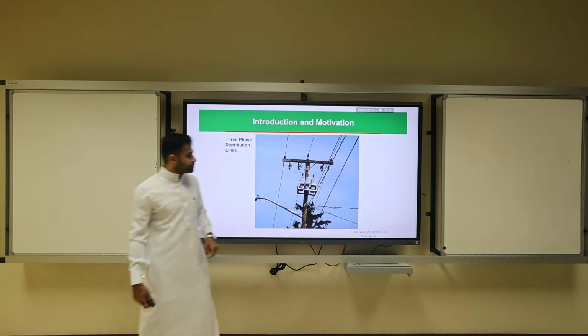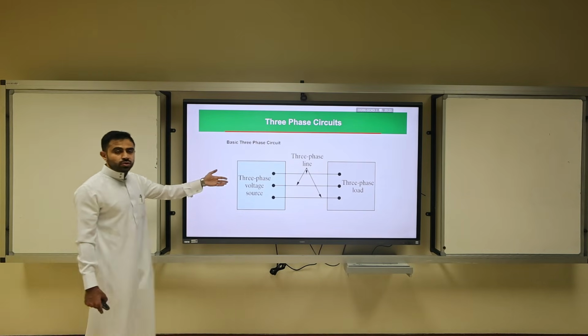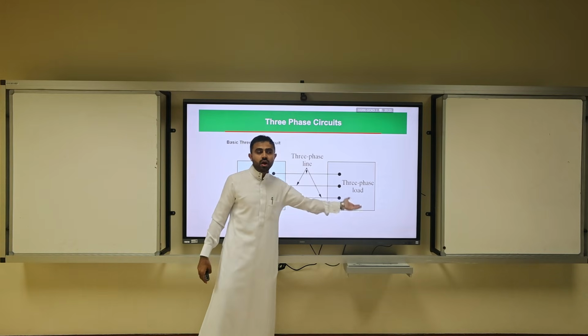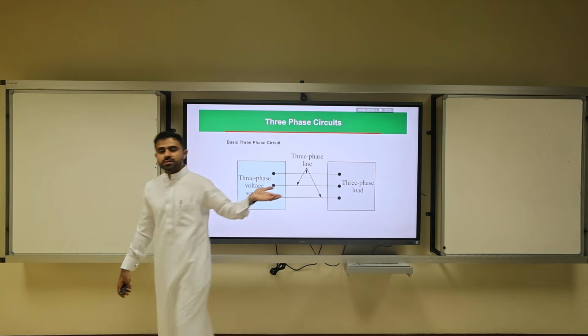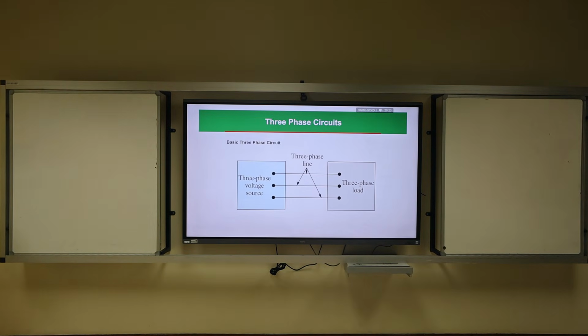Okay? So 3-phase voltage source. If you don't have a split or service transformer, they have to serve a 3-phase load. What are examples of 3-phase loads? Elevators. There are 3-phase motors in there. Mainly motors are 3-phase. And what other thing? Shunt reactors. We call them synchronous condensers. Sometimes we operate them as loads. What else?